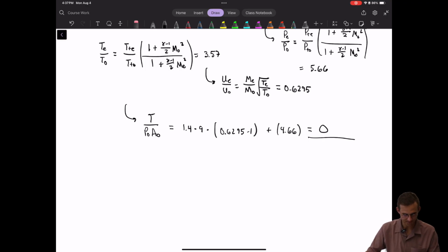Okay, so the first thing that we should do is reduce the throat area until the flow is essentially getting choked in the actual throat, meaning the throat of the diffuser upstream. This allows us to increase the heat addition without violating mass conservation, because the inlet is now slowing the flow down a little bit instead of the shock.